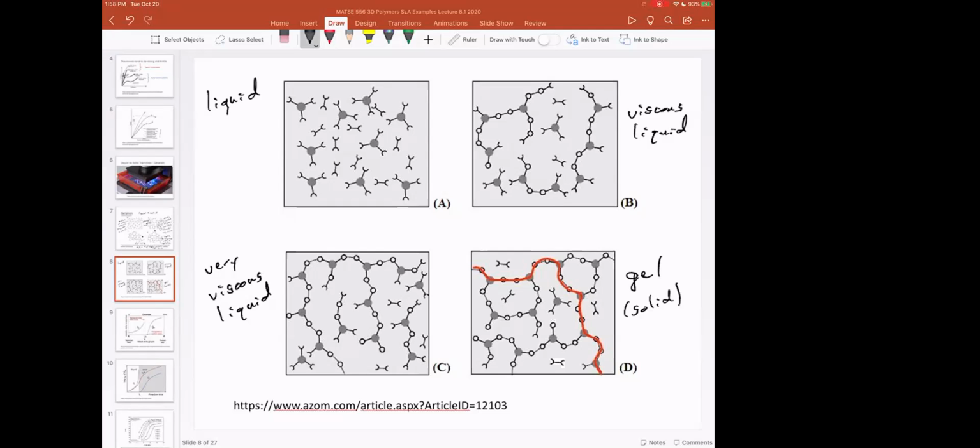So if your resin is unstable, or if you have a lot of light bleed, or if you leave your resin in a clear jar and it cures on its own, this can certainly happen in an undesirable fashion because in order to get these reactions to happen quickly, you need very reactive monomers. You need to have very active photoinitiators.